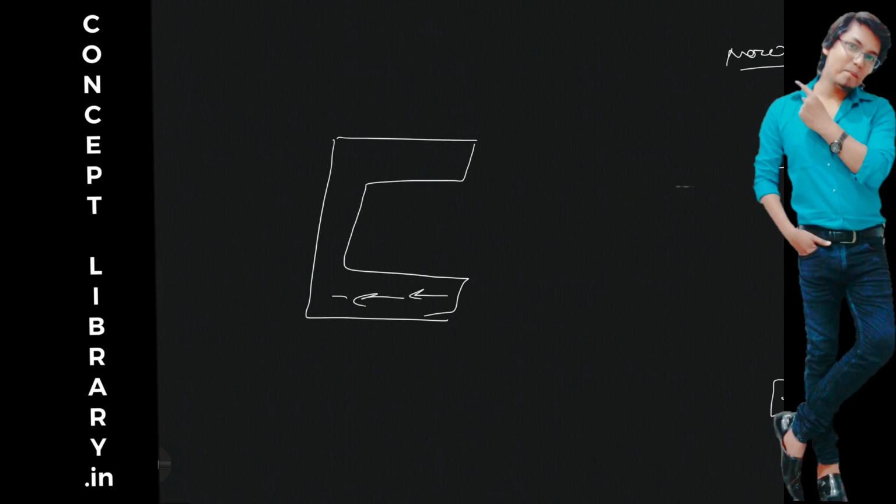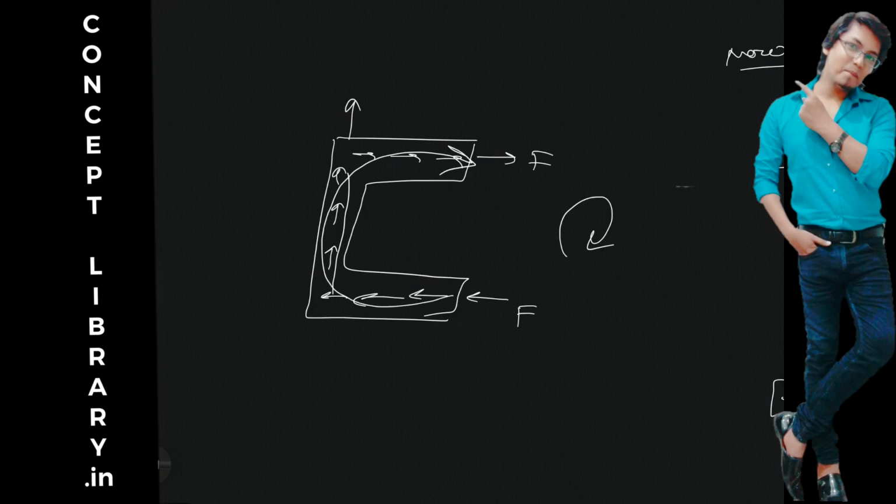Suppose in this channel you have shear flow like this. You can say shear force or shear flow. From here you have shear force in this direction and here in this direction, and in this beam it is in this direction. If you want to vanish the effect of twist, why? How is the effect of twist coming? Because this force and this force are producing the effect of twist like this, correct? So this beam has a tendency to twist like this. I hope I'm being clear.